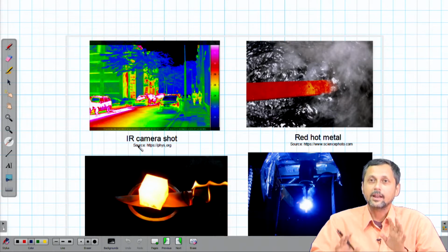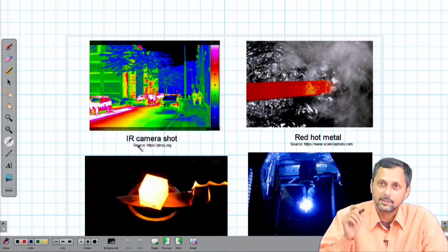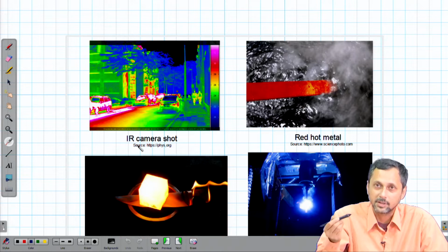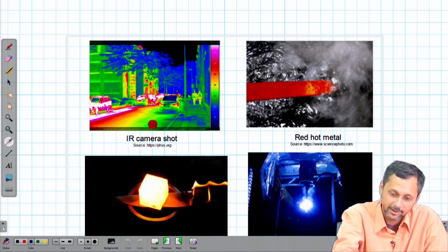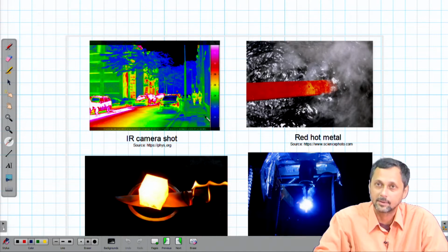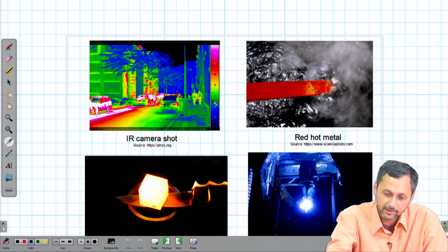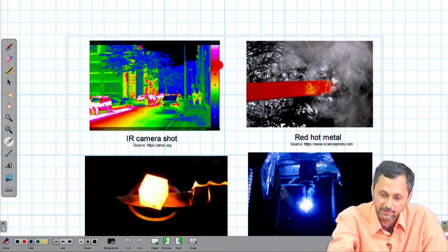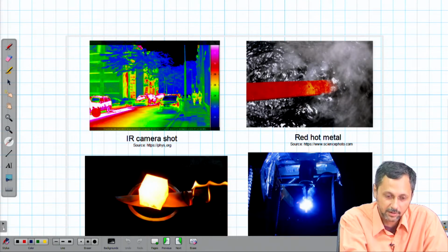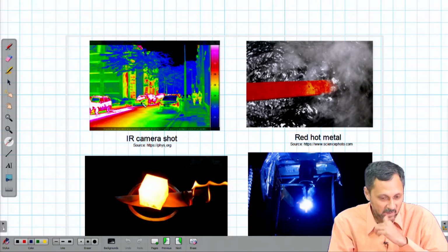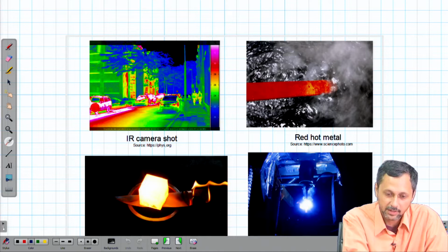Even in the dark, an IR camera can sense the heat radiation coming out of any object, and this is exactly what we see through an IR camera, right. And here that can be converted to temperature. So, we see there is a temperature scale in degree centigrade given to the right. The black is 18 degrees and the brightest one is the pink, which is 32 degrees. We see these cars, the car tire is hot, actually the road above which the car moves is hot.